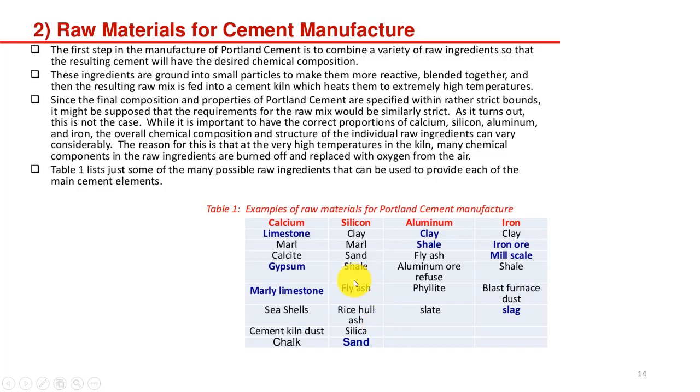So these silica-rich ashes can be utilized as a siliceous material, to be used as a raw material for cement production. Sand also contains the silica, but in crystalline form. The crystalline form is not a reactive form, so you have to make it reactive before adding it into the constituents of cement. So silica present in the sand is maybe the last option to be added.